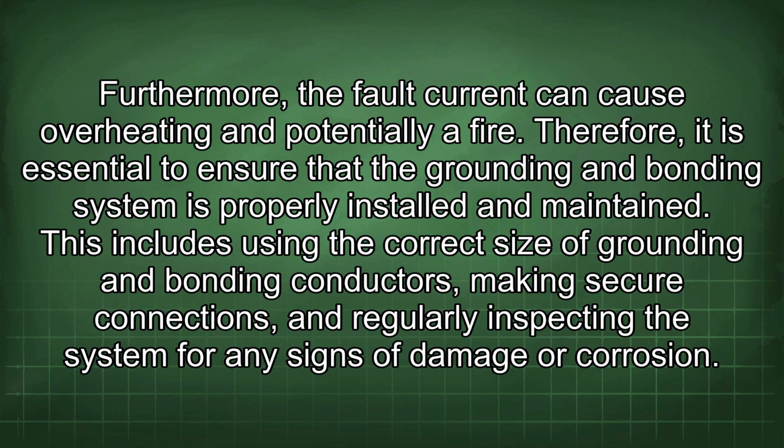Therefore, it is essential to ensure that the grounding and bonding system is properly installed and maintained. This includes using the correct size of grounding and bonding conductors, making secure connections, and regularly inspecting the system for any signs of damage or corrosion.